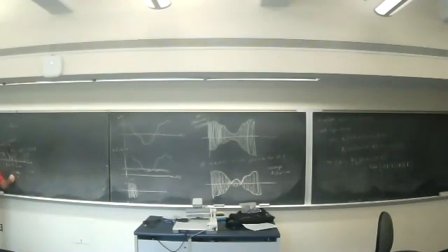This is our transmission bandwidth. BT is 2W, and that is equal to our required channel spacing. Okay, so we'll be primarily comparing these modulation methods based on two criteria. What's their transmission bandwidth? For standard AM radio, it's twice the bandwidth of the message. And the other is how much power do they use? Okay, those are the big things. You have to pay for power. And then the transmission bandwidth determines how many radio stations we can put in a particular spectrum.